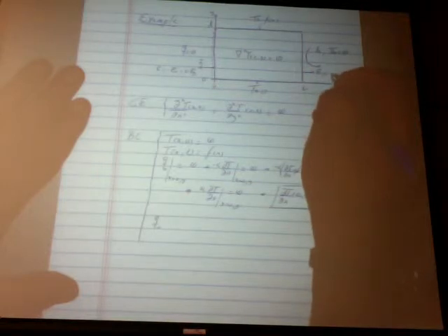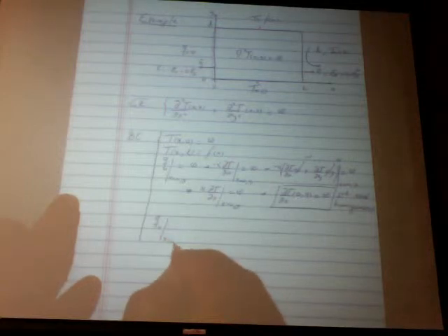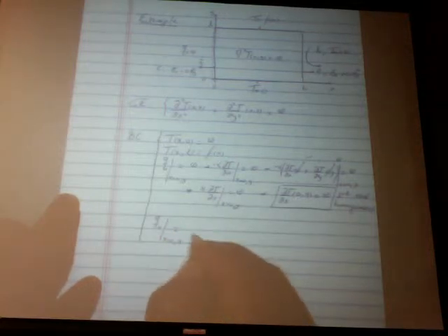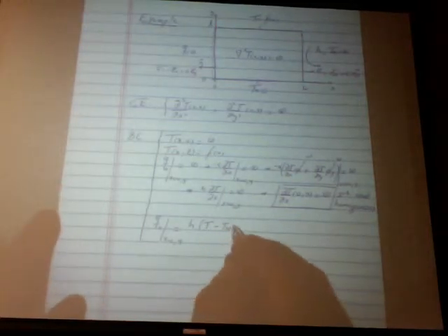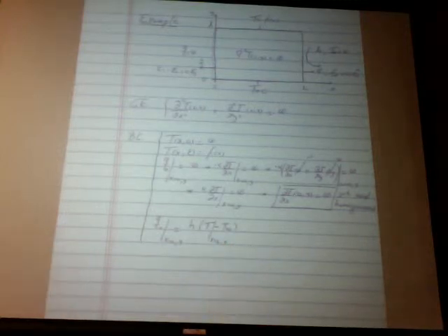The normal amount of heat flux, and again, we have a normal vector on this side, which happens to be positive Ex plus 0 Ey. It's a horizontal normal vector. Qn at x equal L, y is equal to h times T minus T infinity. And that's T at x equal L, y.